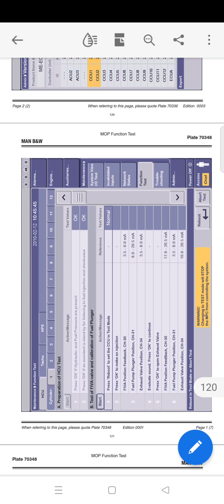So signal value is okay. If dot dot dot, dash dash dash, there are 3 dash in red background, the signal not present, then check the MPC is connected to the network or not. There is any connection problem, loose wire or something has happened. So a red and in that is rectangular shape will appear when this dash dash dash.